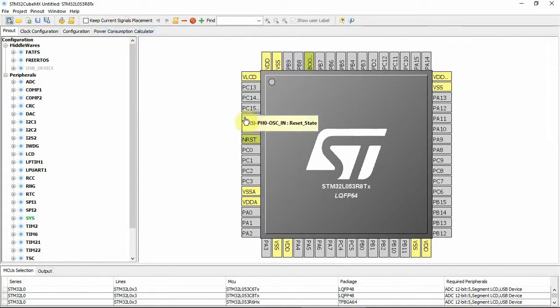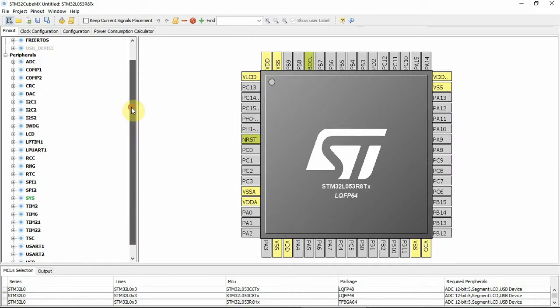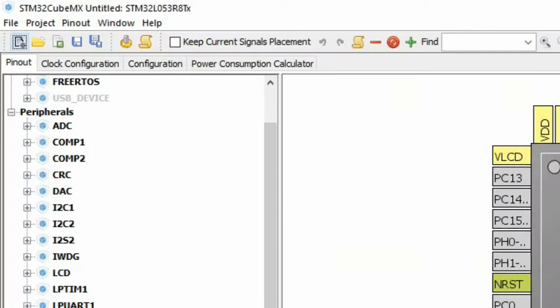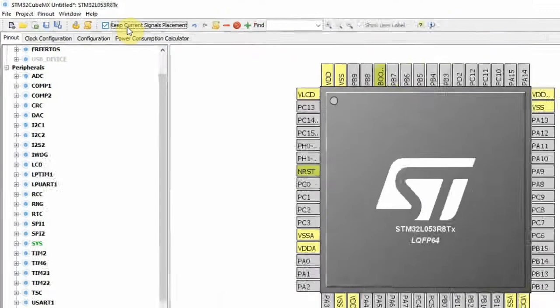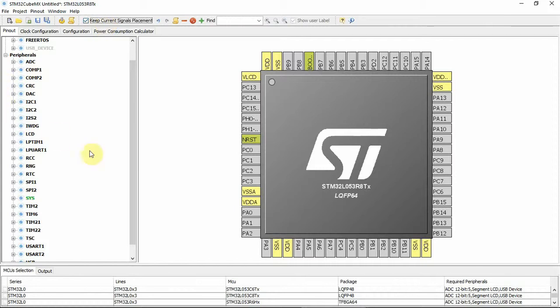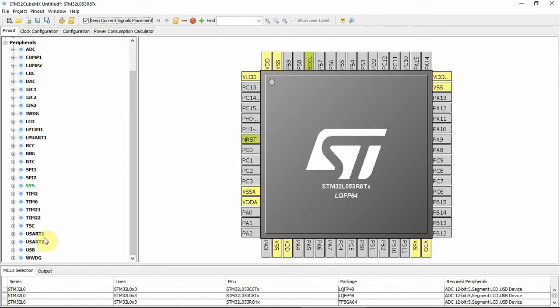This option, because the STM32 has alternate functions, when this option is set, you can see a pop-up balloon: options will not be able to move to alternate functions. So if there is any function that can be, for example the UART, at 2 different pins, when this is set, CubeMX will not change the pinouts to the alternate functions.